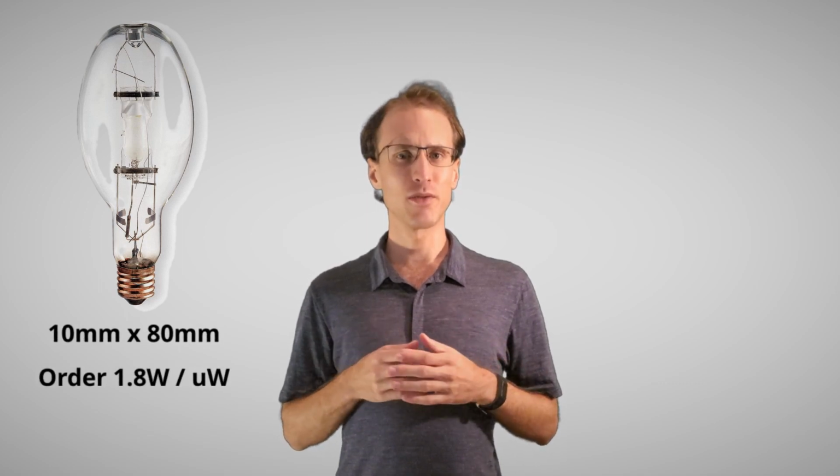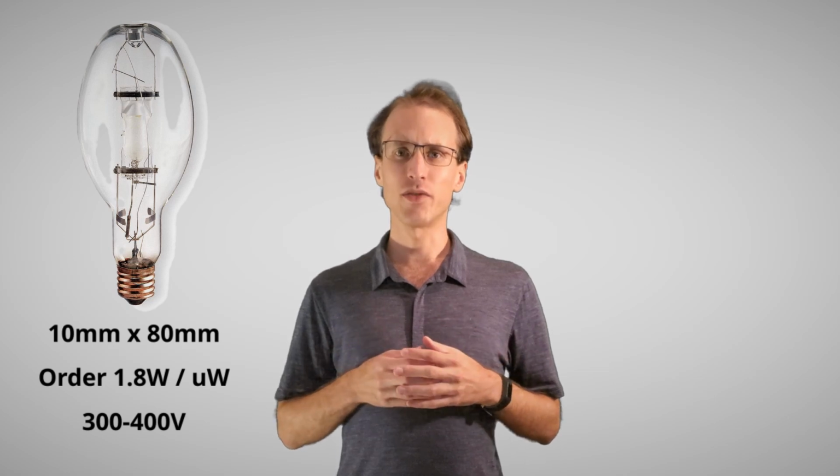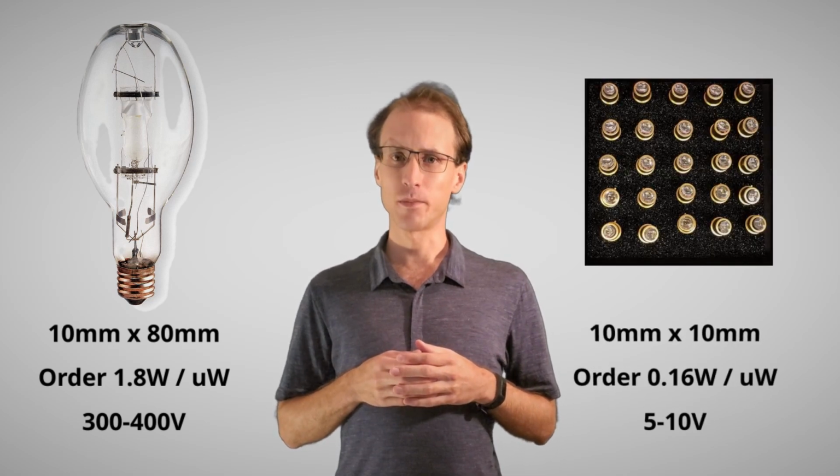What are these changes? Well, the LISA Pathfinder CMD design used mercury lamps to provide the UV photons, which are large, power-hungry, and complex to use due to their high voltage drive. The LISA CMD will instead use a new technology, UV LEDs.